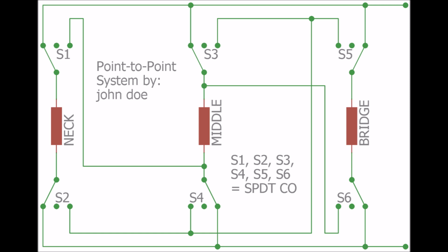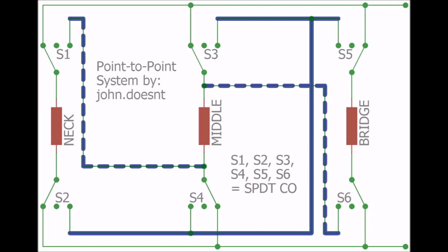Observe that there are now 2 internal buses that were created in our circuits. The buses function either, 1. To connect 2 pickups in parallel, which in turn allows the pair to connect in series to another pickup, or 2. Establish a series path between 2 pickups, and for 3 pickups. This feature of buses will be further exploited in another switch system, which will be discussed later.